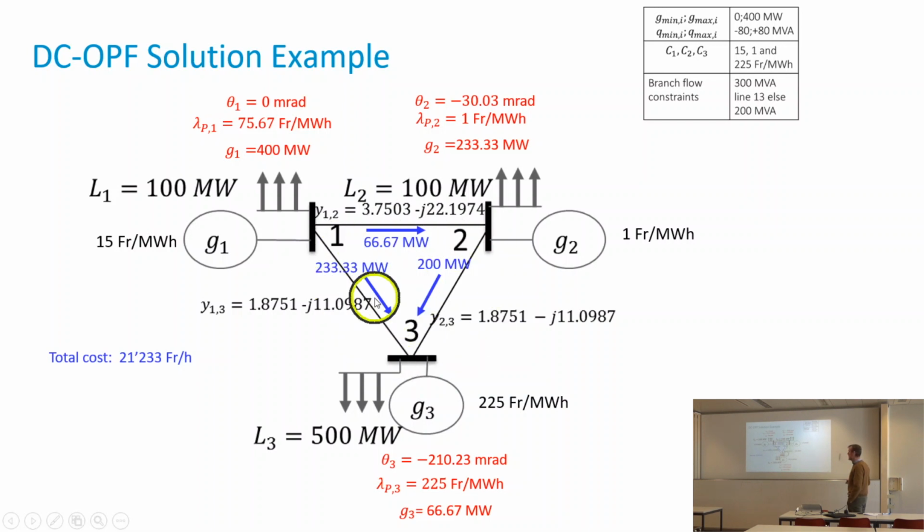So once I've done a DCOPF and I've decided, okay, I will do this and that, we still need to reincorporate the losses. So the way this is done in electrical markets is to do a load flow from the generators. So we say, here are the generations here. We will compute the losses, and then we will need a bit more generation due to the losses, and this will be reattributed as a flat tax to everyone. The tax to be able to use the grid is to pay for the losses here.